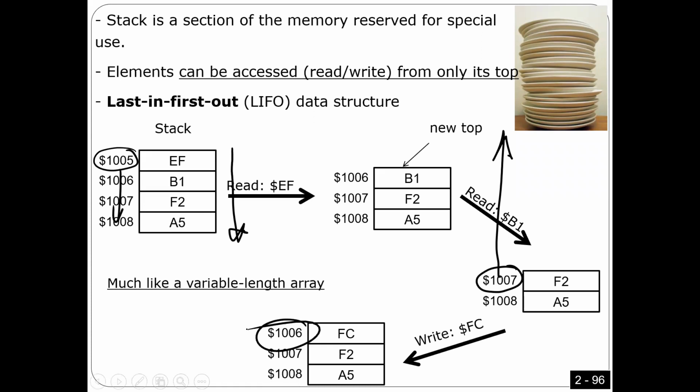The way I'm going to design our stack is to grow toward smaller addresses. I start from a certain address, and every time you write, I go toward the lower addresses. By the way, this is a design choice, maybe what we do in our microcontroller. Another microcontroller may design it the other way, and that's no problem. It's still the same concept. When you study another microcontroller, you may see stacks that grow from small addresses to bigger addresses.